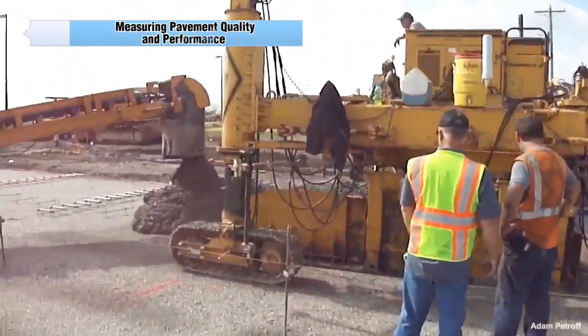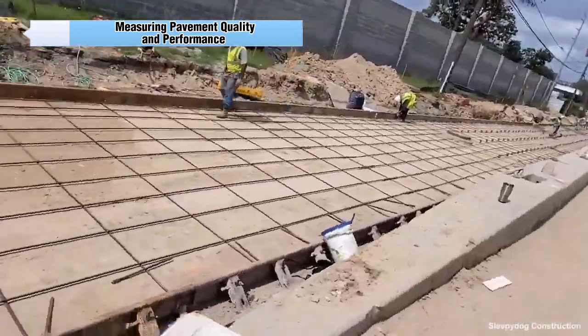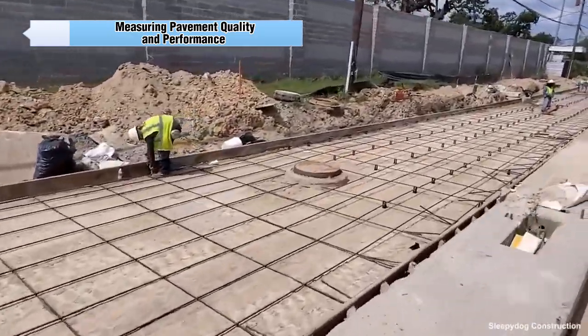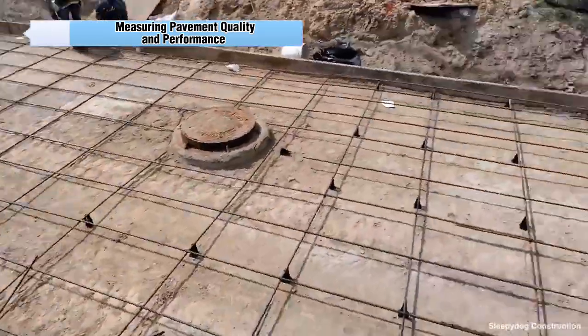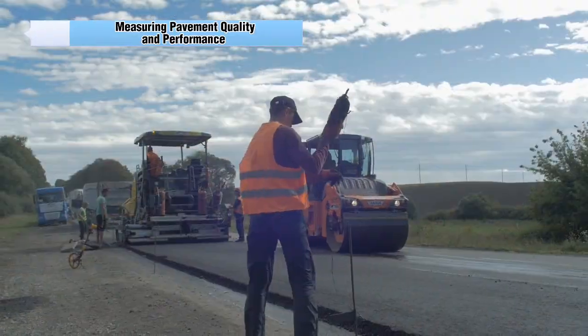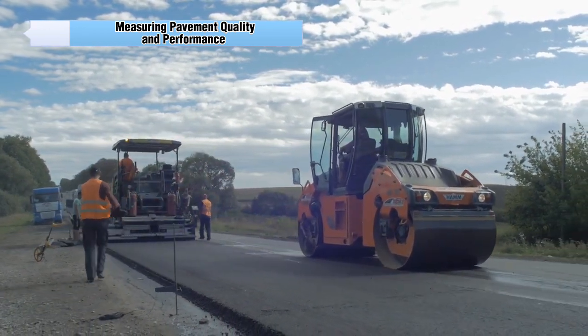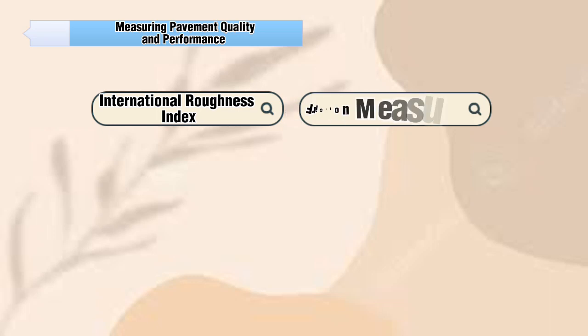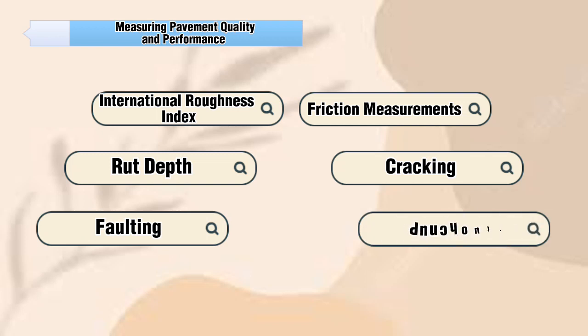Measuring pavement quality and performance. The design procedure for pavements originally focused on the Pavement Serviceability Index as a measure of pavement quality. Efforts have been undertaken to develop quantitative measures of pavement condition that provide additional insight into pavement quality and performance and that correlate with the traditional Pavement Serviceability Index. Some factors that are regularly measured by highway pavement agencies now include International Roughness Index, friction measurement, rut depth, cracking, faulting, and punch-outs.